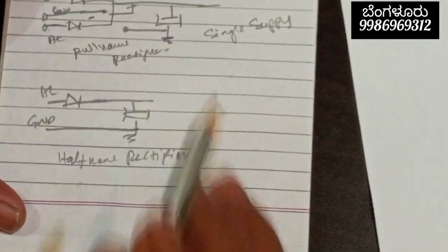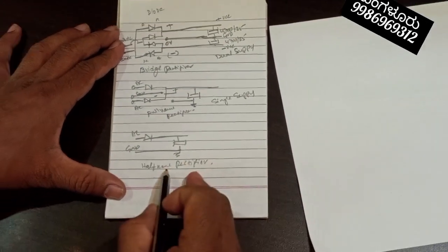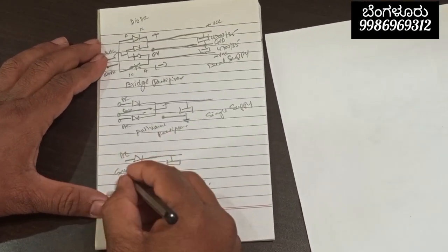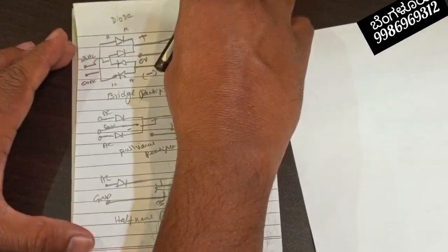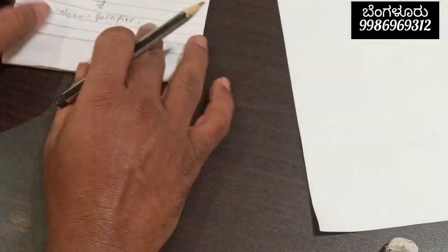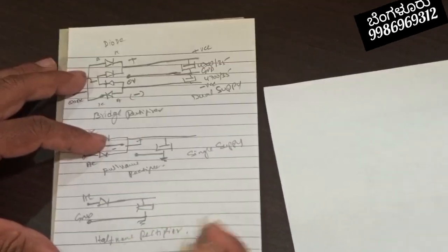So this is it. So this is a single wave, half wave rectifier, full wave rectifier, and bridge rectifier. The half wave rectifier can be used for a fan. If you have 12 volt 0 12, the other tapping that I have shown here, 0 12, this can be used for this. There only one single diode is enough.